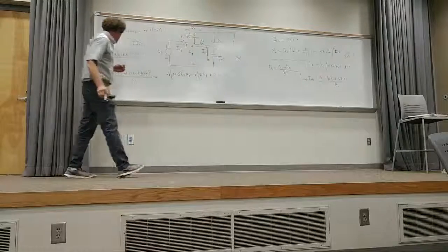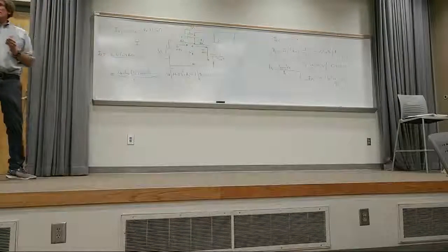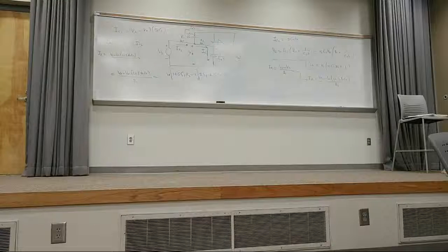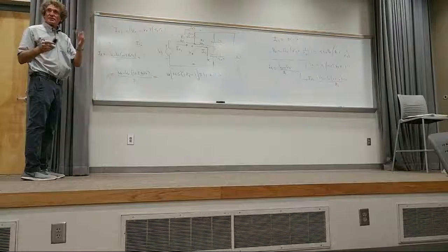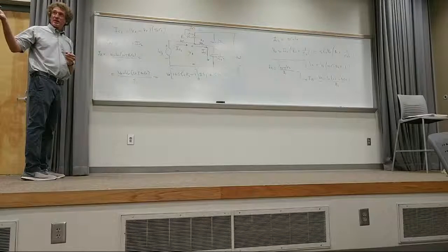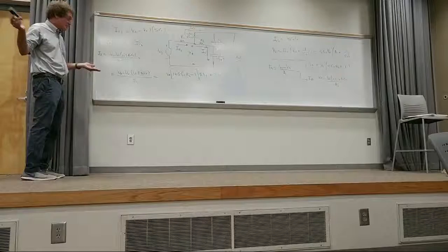Now, just take a look at this for a second. I'll clean this up. You have to see, now isn't everything in terms of V out and Vs? It's a bookkeeping kind of problem, isn't it? Just keeping the books. It gets a little awkward. Now, everything's in terms of V out and Vs, correct? So if we get the ratio of V out to Vs, don't we have the transfer function H of S, class? You all follow me what I'm saying? If you take the output over the input voltage, that's what we want, right? So now we simply divide everything by Vs.